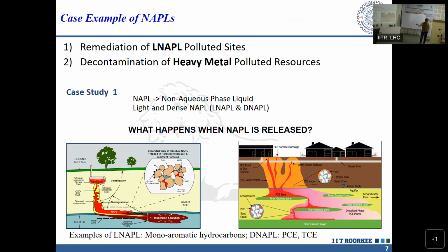Maybe a few ml, a few liters. And that is going to be a long-term source of contamination for the groundwater. So whenever somebody is extracting groundwater from the down gradient side, or even from the up gradient side of this leak, opposite to the direction of groundwater flow. Here the groundwater is flowing from left to right. Contaminants can also travel in the opposite direction because of molecular diffusion. So when somebody takes out the groundwater here, we can see not only the groundwater but also the soil air coming from this polluted zone, which also contains traces of this pollutant.